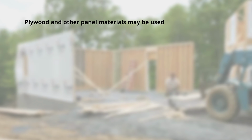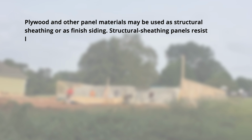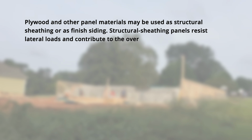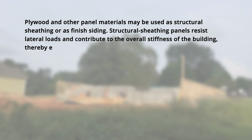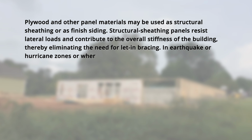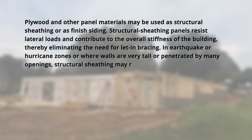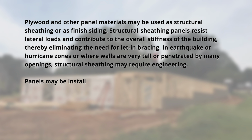Sheathing. Plywood and other panel materials may be used as structural sheathing or as finish siding. Structural sheathing panels resist lateral loads and contribute to the overall stiffness of the building, thereby eliminating the need for let-in bracing. In earthquake or hurricane zones, or where walls are very tall or penetrated by many openings, structural sheathing may require engineering. Panels may be installed either vertically or horizontally.